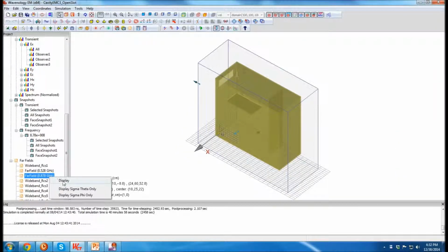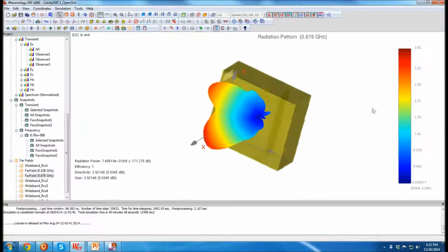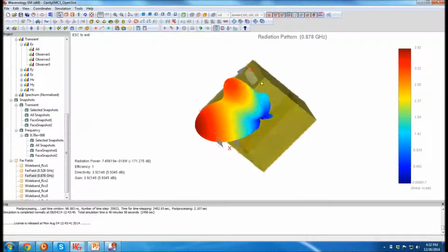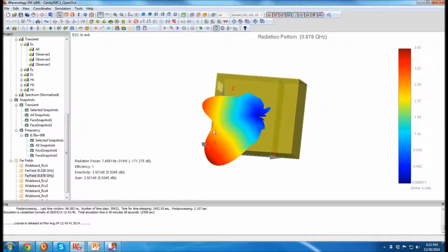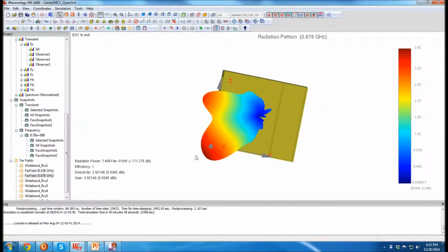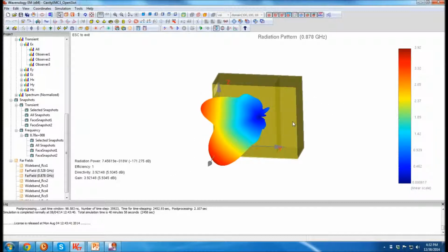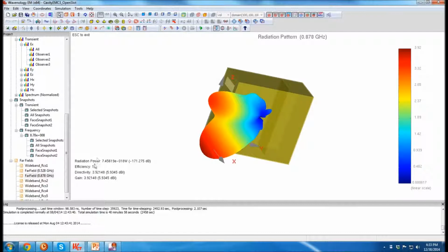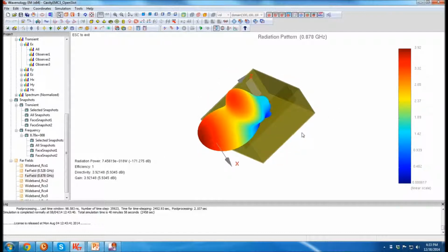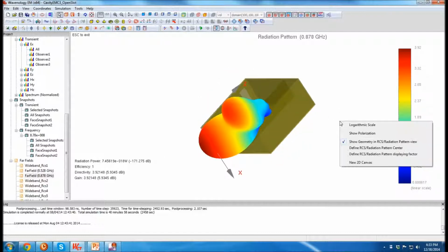Again, at this frequency, if you display that, you will notice that in the far field, the strongest point is right around this angle, around 45 degrees down. So if you observe the field really far away, like 30 meters away, you will see which one is the strongest point. Okay, so that's how the radiation pattern looks like when you do the EMC.